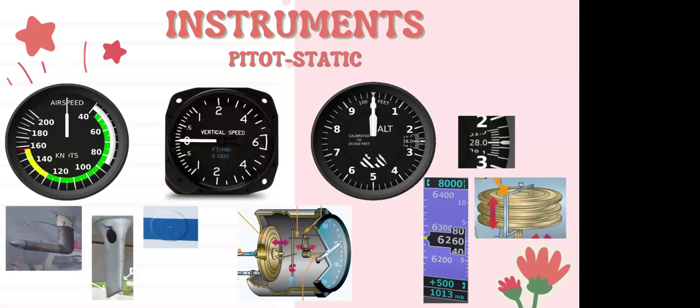So, for example, let's say we're going up in altitude, right? So less dense air. Well, we go up, that diaphragm immediately feels that less dense air. However, since we don't have an immediate change in the case, we momentarily have denser air in the case than we do in the diaphragm. Well, what do you think that does? It compresses the diaphragm. And that's why we also sometimes say that the VSI has a lag, which it does, because it's built to be that way.